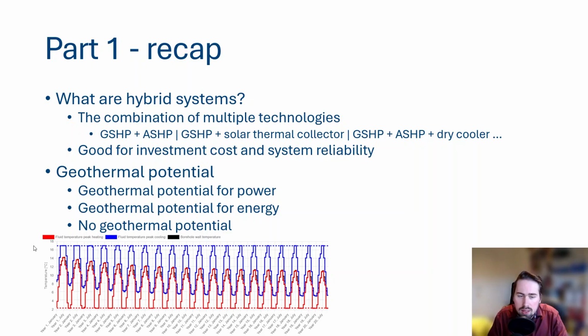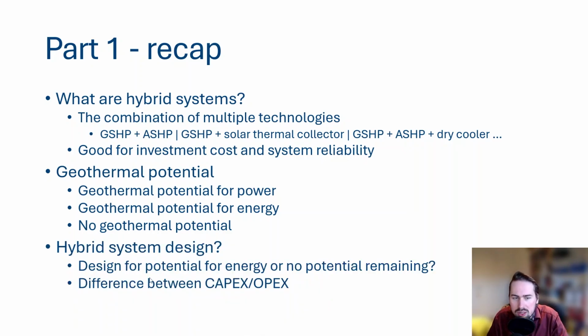So if we then circle back to our question of hybrid systems, we discussed that in order to design a geothermal hybrid system, the main question was, well, what percentage of my building loads, what share, can I get with my borefield? And it really depends on how you design the borefield.